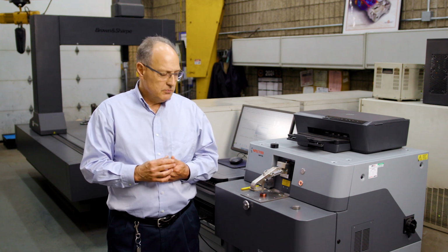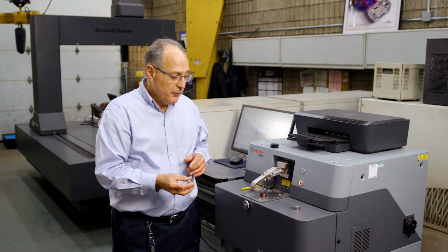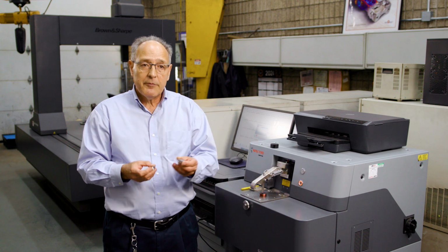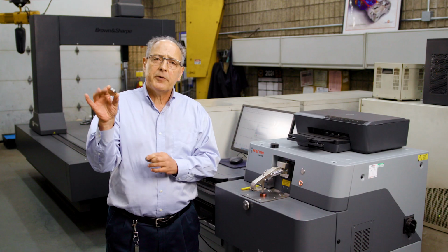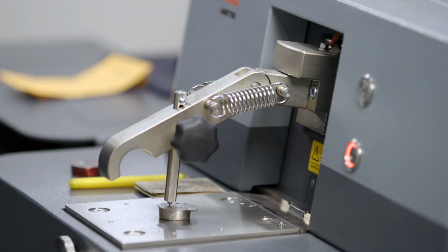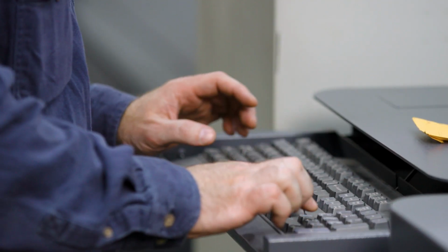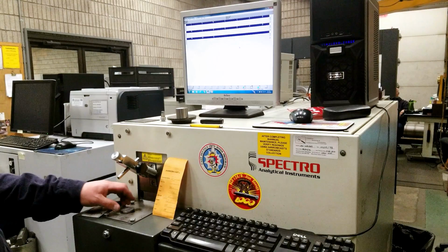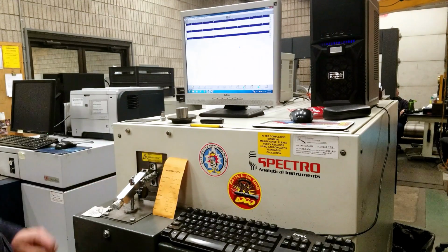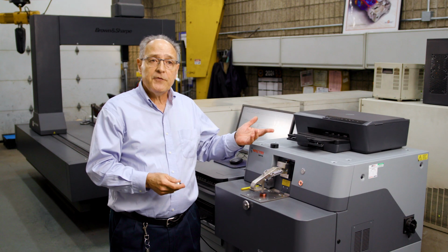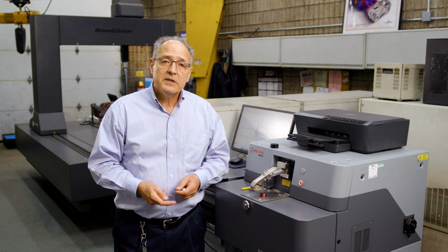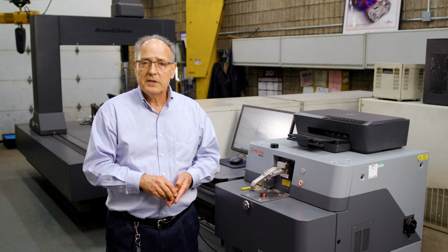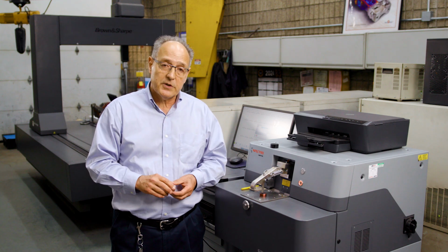How does that work? Well, we have to teach the spectrometer, right? So we have standards, for example, 0.2% copper. This one, 0.8% copper. If I burn these standards on the spectrometer and I tell the spectrometer this one has 0.2, this one has 0.8, now the spectrometer knows it has a curve. If the next sample has 0.5, the spectrometer is going to look at the light and tell me 0.5 copper. That's how the spectrometer works, and it analyzes 22 elements for us.